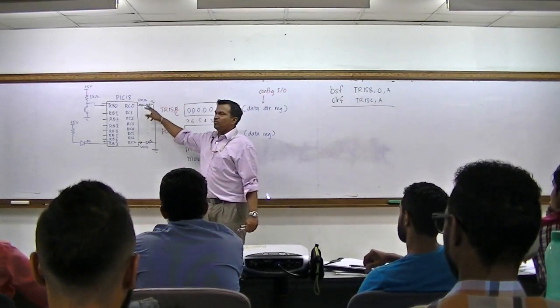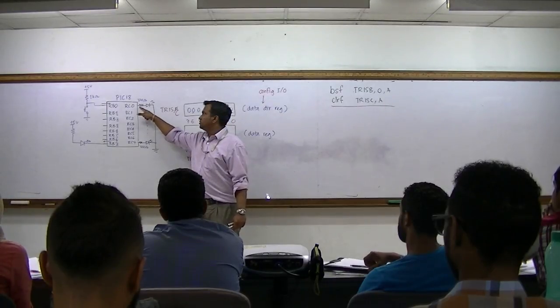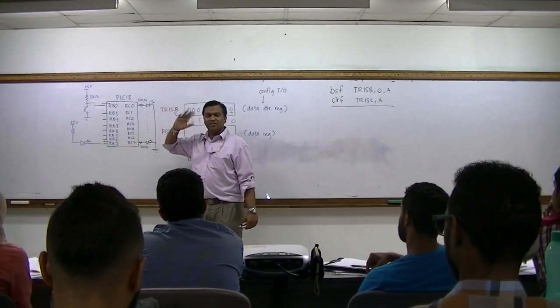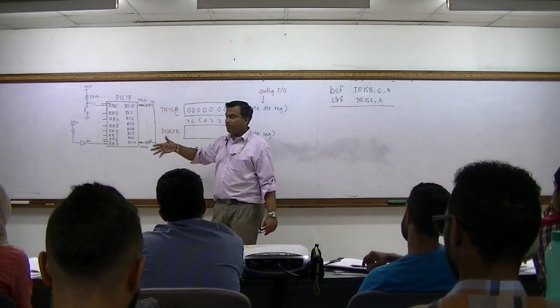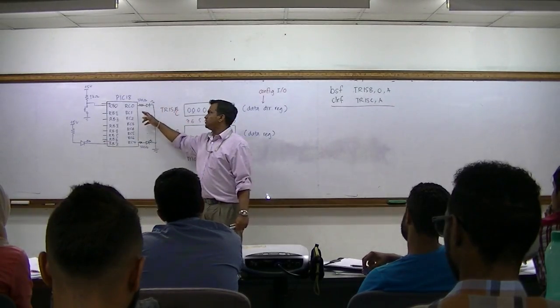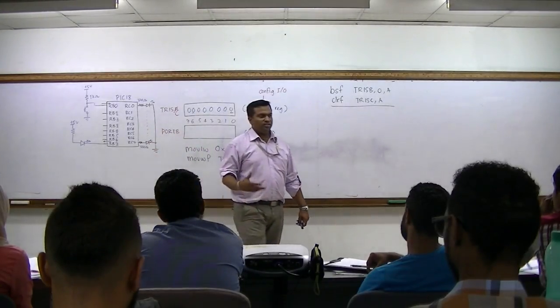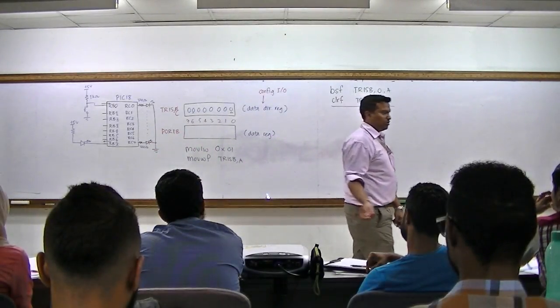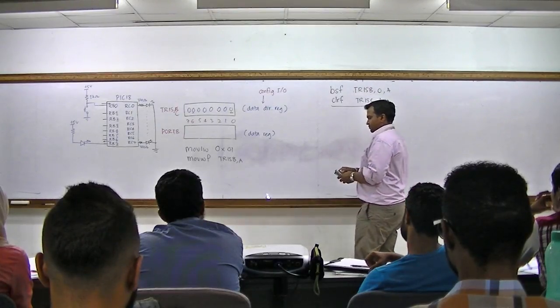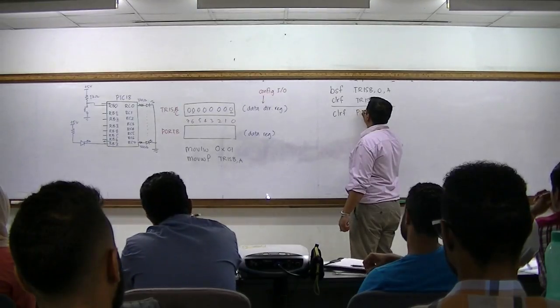this one, in order for you to turn on the LED, you need to supply logic. We want to initialize it. We want initially all these LEDs to be off. So we must supply logic 0. So what is the value that we should write to port C? 0. So how can we do that? Clear at port C.